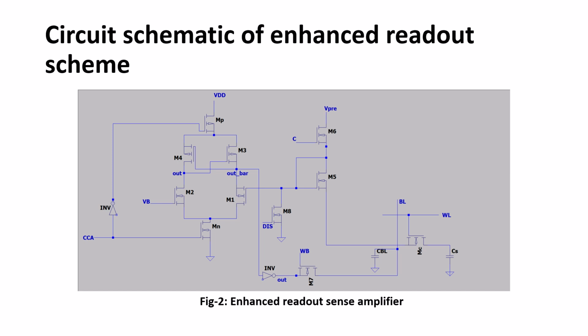So the current coming from this M6 and the current flowing through this M6 is more, there is a difference. In order to accommodate a balanced current, this Vg has to decrease in order to maintain the same current which is flowing through this M6. And again this is fed to this current comparator, and there is a reference current already flowing through this.